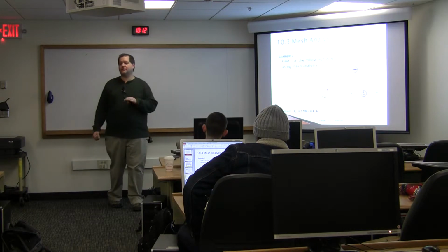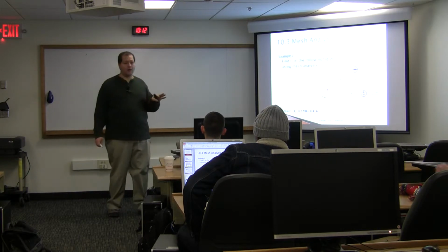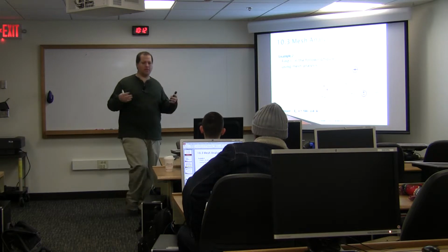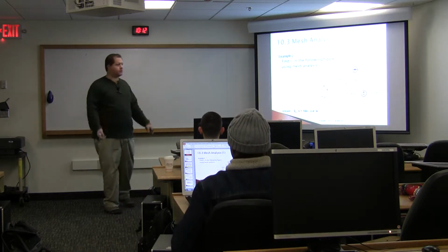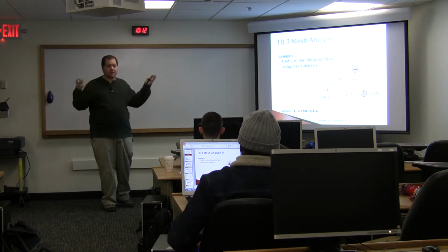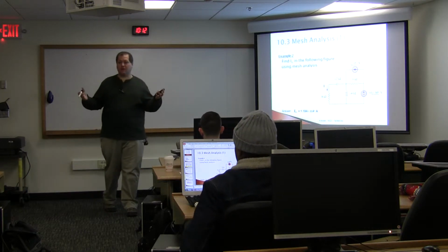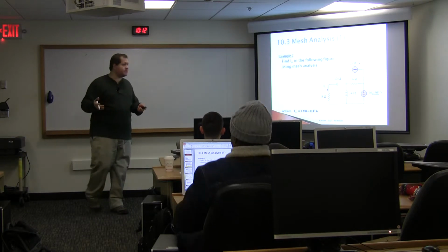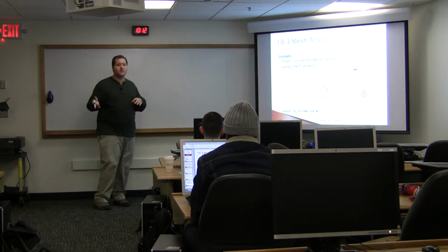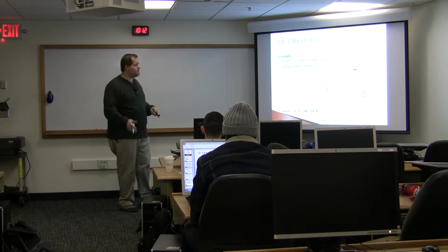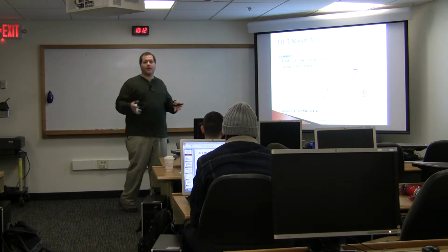However, if you were to build this circuit in the lab, again, an omega of 1 could be a little bit challenging to generate on your equipment. You might not be super happy with the results. So you might want to pick something like 60 hertz, which is what it would look like if it was doing power, right? 60 hertz is pretty reasonable. Again, just convert from 60 hertz into omega, right? Omega is 2 pi f, so you've got to multiply 60 by 2 pi. But whatever it is, pick an omega, and then you can go from there.